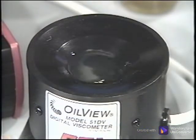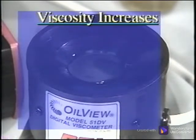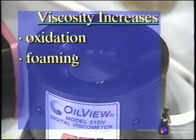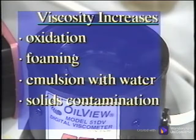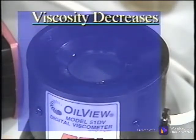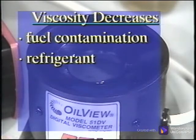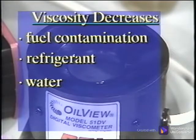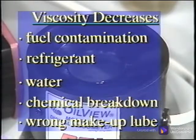Oil viscosity in a machine can change due to chemical, mechanical, or process influences in the system. Viscosity increases due to oxidation, foaming or cavitation in a pump, emulsion with water, solids contamination, and the wrong makeup lube added. Decreases in viscosity are caused by fuel or solvent contamination, refrigerant leaking into the system in air conditioning systems, non-emulsified water contamination, molecular shearing or chemical breakdown, and the wrong makeup lube added.